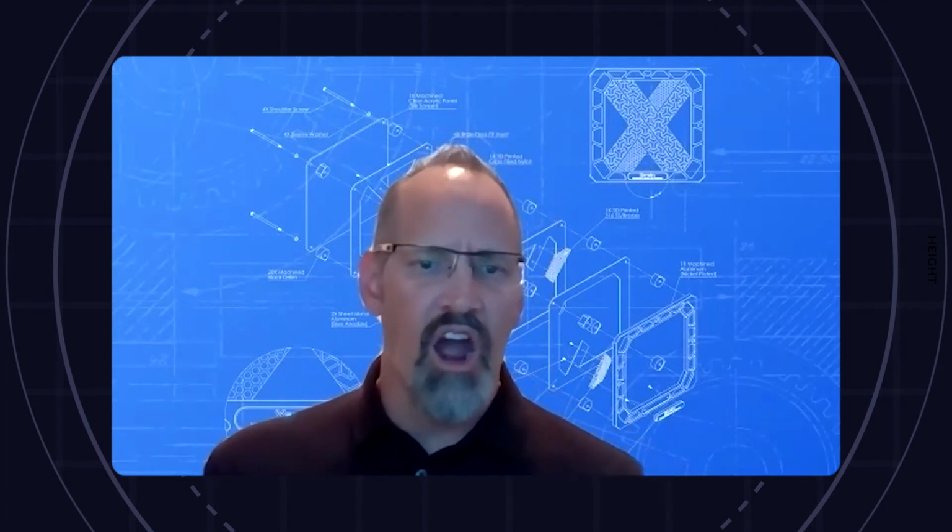In today's episode, we will be covering a vital part of our workmanship standards, threads. Any internal or external threads for metal fabricated parts are subject to Xometry standards, as well as machined threads regardless of cutting method, i.e. cut, milled, or rolled. These standards ensure that threads are cut according to the provided drawing, are free of defects, damage, contamination, and are capable of accepting the go gauge and not accepting the no-go gauge more than 3 turns.